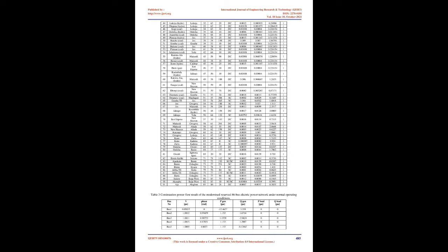This allows the solution of the power flow problem for stable (upper) and unstable (lower) portions, equilibrium points, of the PV curves. The continuation power flow method uses a locally parameterized continuation method for solving nonlinear algebraic equations known as path following methods 14 to 17. The continuation power flow analysis uses an iterative process involving predictor and corrector steps.